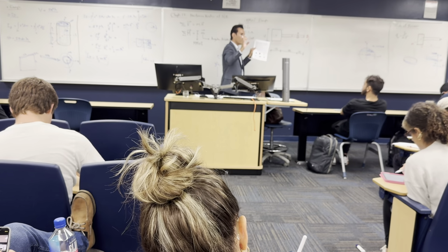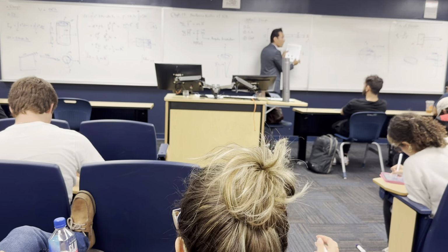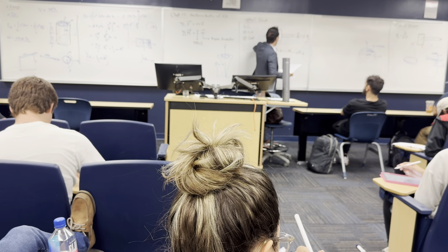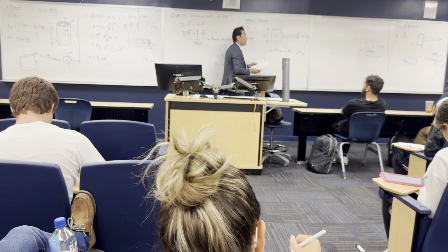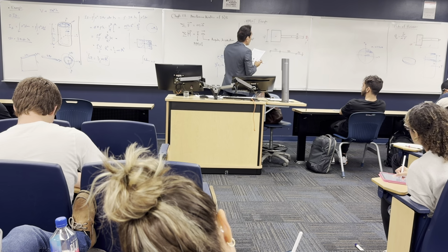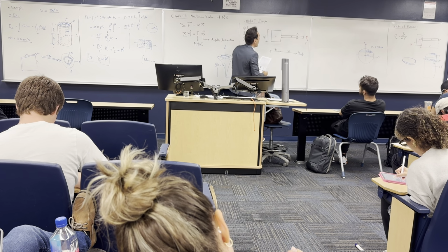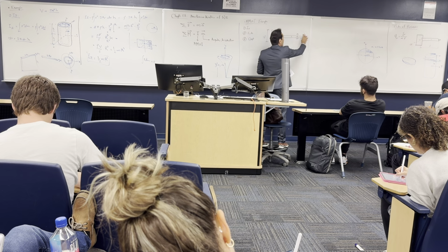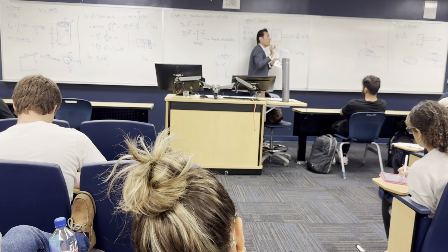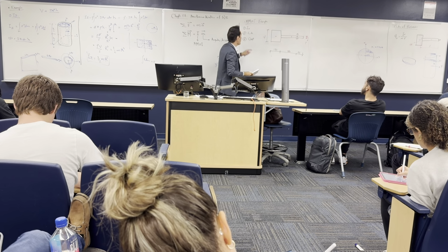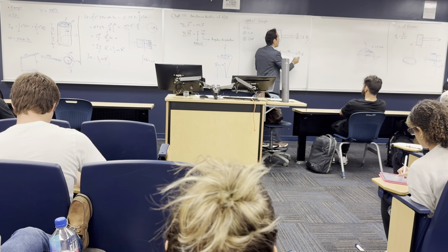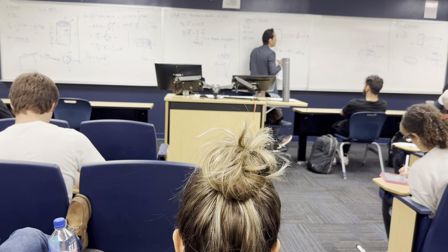It's very, very thin, so we call it a bar, and it has a special moment of inertia. It's only a function of the length, not of the width. But this one has a width and depth that are the same, so definitely it has Ix and Iy. All right, and Izz of this bar is 0 because we neglect the mass about Z, because this is very, very tiny mass. So if the mass is very, very small, dm is going to be 0, so I is going to be 0 because we neglect the mass around the z-axis. But right now we are not calculating about the z-axis.